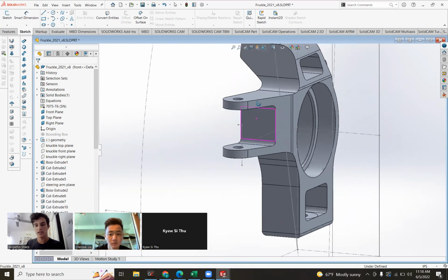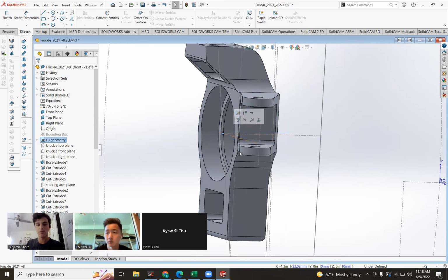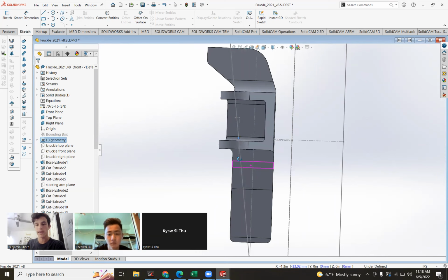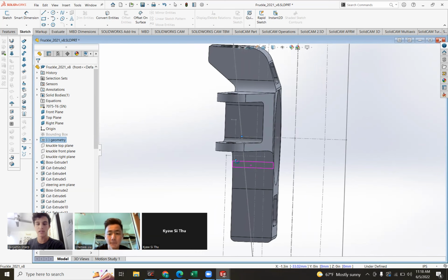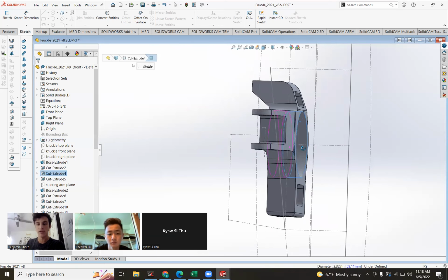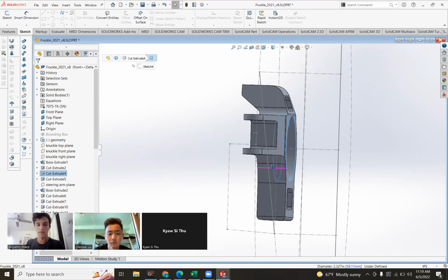But then also an interesting thing to note is this center point, which I said was a central part of the knuckle, is not actually modeled anywhere in the knuckle, and it's not even in the middle of the knuckle. It kind of just floats in space, and it has to because the really critical mounting points are here and here, but above this mounting point, you need a straight portion of material because this has to be straight. So you can't have the whole thing curved or this won't install.